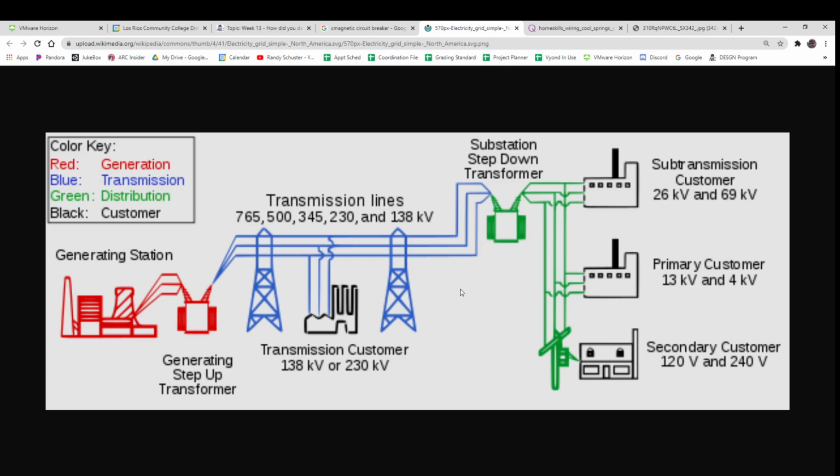So let's say your circuit breaker was set for 10 amps, and you just had little wires coming out to a few small things, then that circuit breaker won't kick until 10 amps are used. And if your electrician used wire that was too small, it will burn up before your circuit breaker goes. Oh my. So you can ask somebody about that. That's kind of a common thing of what happens. But yeah, that's how it happens.